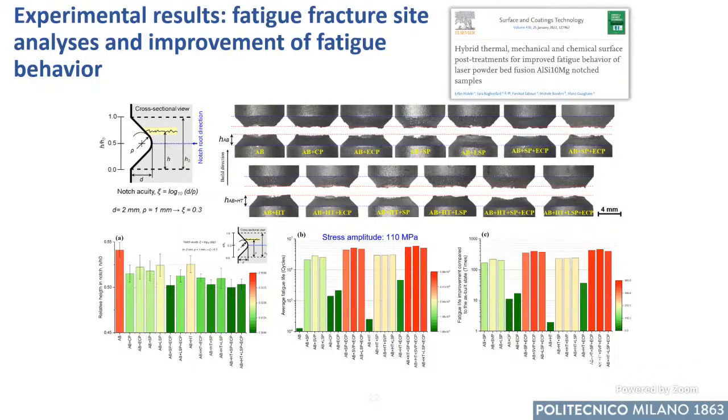we have got in terms of fatigue strength. The stress was fixed at 110 megapascal. And here it's interesting to see that the failure cross section is not the minimum one. And it's in the as-built material. What does it mean? That due to the quality of the surface, the crack starts not on the minimum section, but in the downward phase. And this is strictly related to the quality of the surface we have achieved by means of this process.